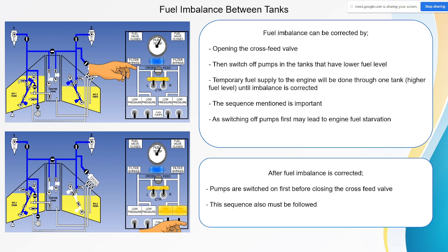But for larger aircraft, you are taking a lot of fuel, let's say from KL to London, 18,000 kg of fuel. This already exceeds the limit of the landing weight. Maybe they just have to dump a bit, like half of it, 10,000 kg, or 5,000 kg. This is in case the aircraft is going a long distance and the fuel they take is above the maximum landing weight.